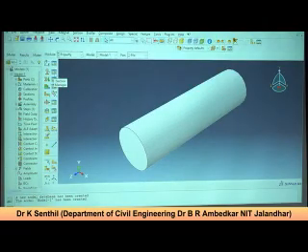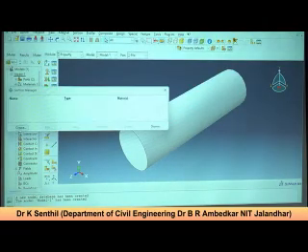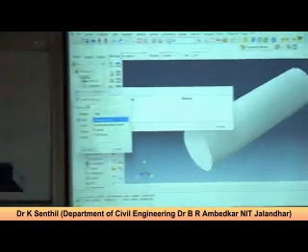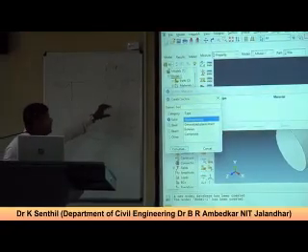Now you have to give the section. So you go here, go to create section, and here let's say soil, it's homogeneous. See, here we have options: if you are modeling something like water, then the Eulerian model is more suitable. Otherwise, the soil we treat as homogeneous. Am I right? The soil will be treated as homogeneous. If you have different layers, then you create either partitions or separate models.